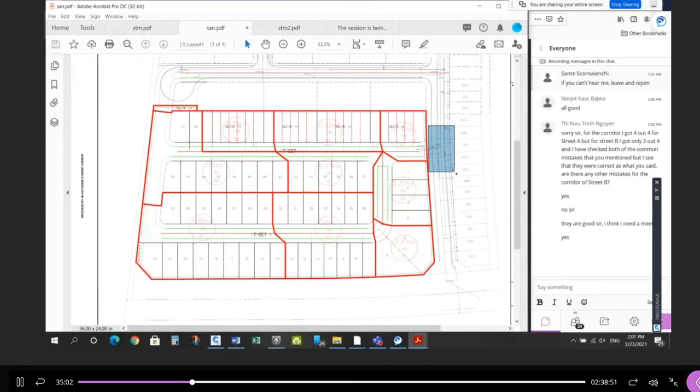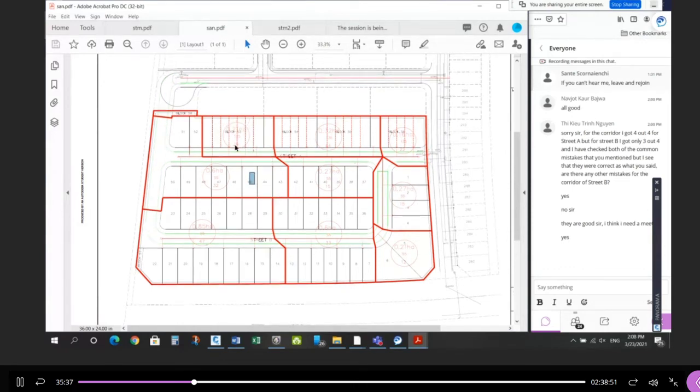Because at a glance, it doesn't take long to see if you know what it's supposed to look like. It doesn't take long to see whether there's something that really doesn't make sense. And this is a big problem. This is wrong and this is wrong. Okay, this is a drafting thing, but it's sloppy. But these two are critical. These are big issues that, in my opinion, I would deem embarrassing. You shouldn't do that. It doesn't make sense. And then there's data missing here. There's that one drainage bubble missing here. And don't forget townhouses versus singles and so on. Okay, any questions about the sanitary?